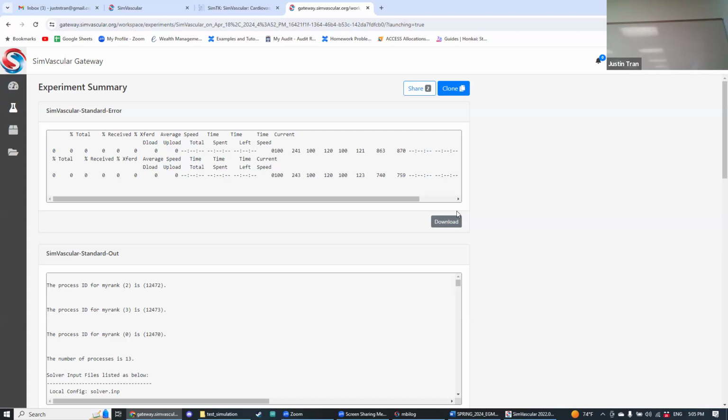Right here too. Oh. This model is actually kind of clipping into itself, so this might be causing an issue too. You can try to look through your model visually and see which vessels are doing stuff like that. Maybe remove them first, then recreate the model and remesh it. See if that works. I would say this vessel is probably an issue. Somewhere down there. Like this one? Yeah, that's probably an issue.